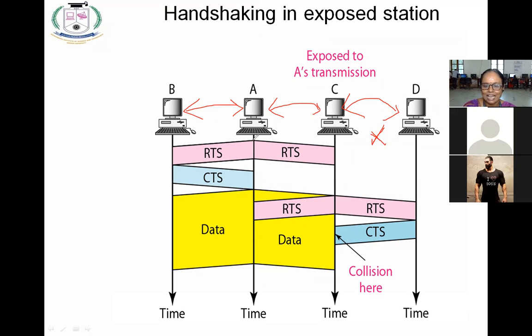First, I am sending RTS. And while I am sending that RTS, the acknowledging CTS signal will be received. So what happened now? A will communicate with both station B and station C. Once I want to communicate with D, again in the C coverage area, A and D, it is sending RTS now.